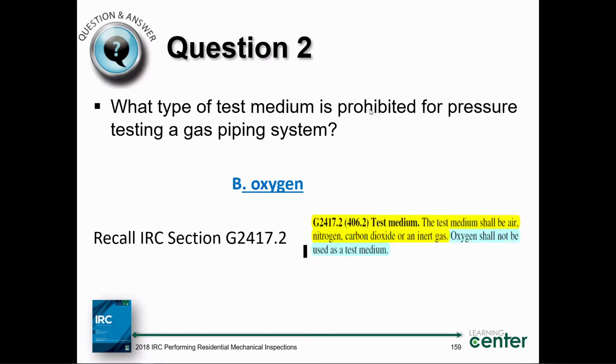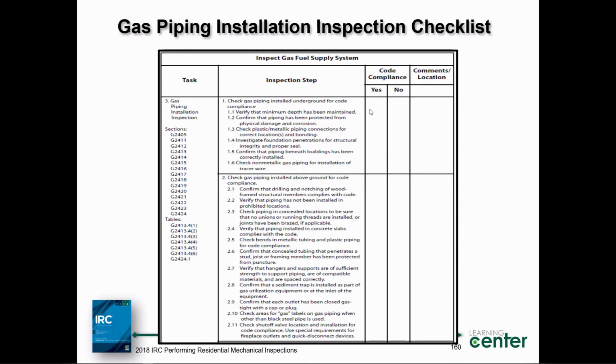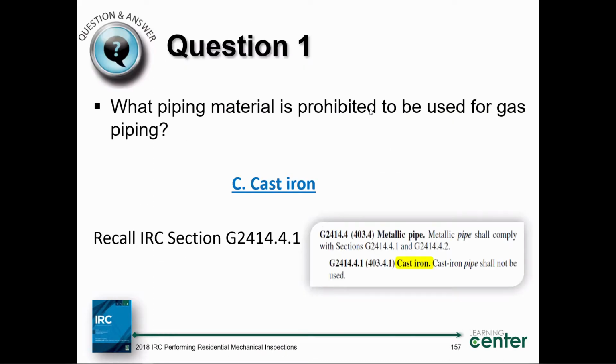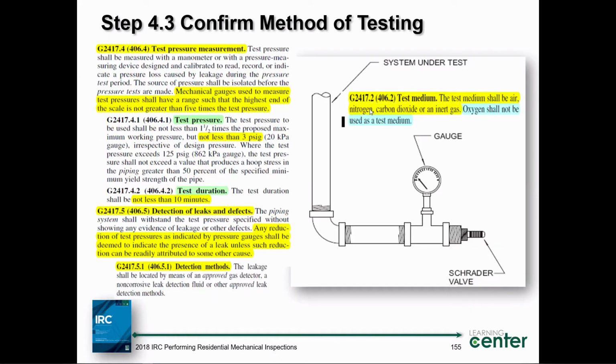Jerry, is that only required if there's a leak and if there's a drop in the gauge? No. Sometimes, when you have this gauge on here, Doug, you will not see a pressure drop, or only a very small increment, depending on how far apart the increments are on your gauge. So you may not notice a very slight pressure drop.